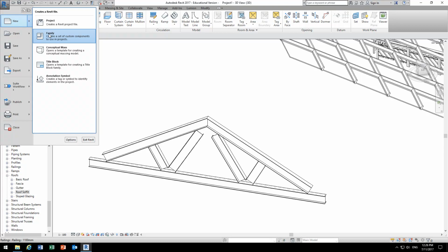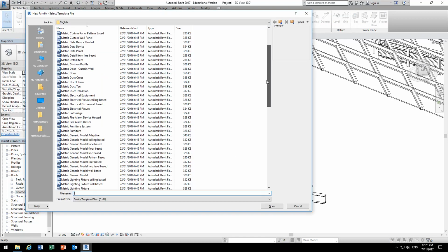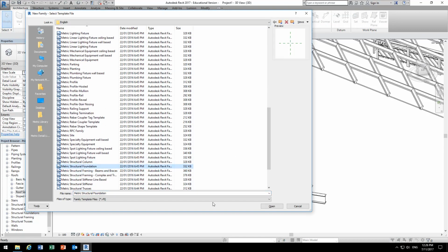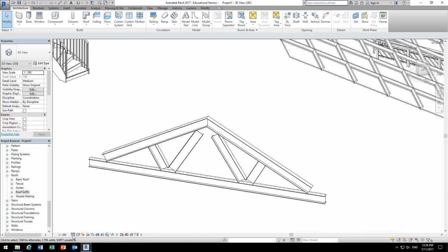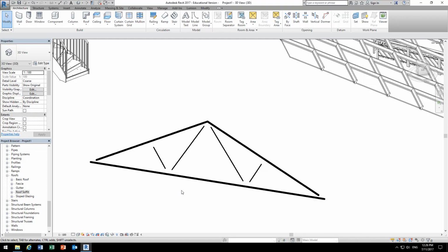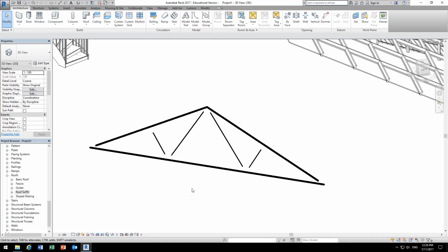Yeah, I normally model them, especially if it's timber, just to get the joints right. So I model them. And you can still make it structural. You can still use the structural templates. What you'll find as well, though, with those structural elements, they do things like this. Now I can show you how to fix that, but if you make it yourself, you don't have to worry about that issue. Do you know what the problem is there?